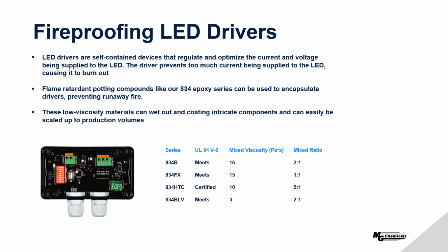These are all two-part epoxy systems that have at the very least been tested and passed the UL 94 V0 standard within our internal lab testing. They're all also fairly low viscosity compounds, so they're able to wet out and cover all the intricate components of the driver circuitry.